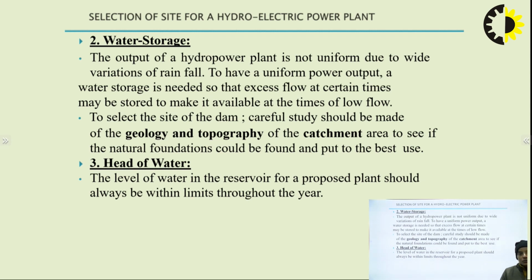To select the site of the dam, careful study should be made of the geology and topography of the catchment area to see if the natural foundations could be found to put to the best use. Okay, so if a natural catchment area is available, that is the best site to select for the dam.